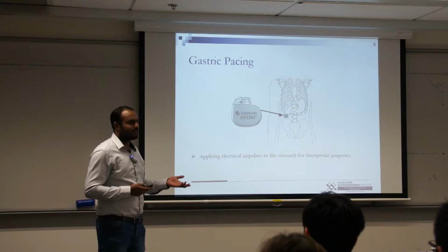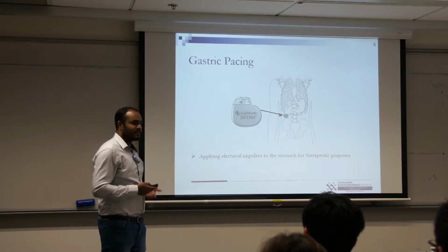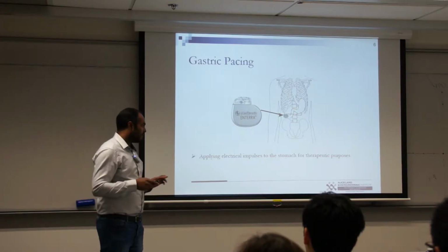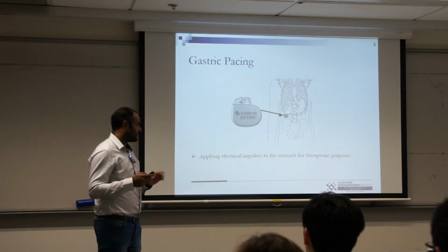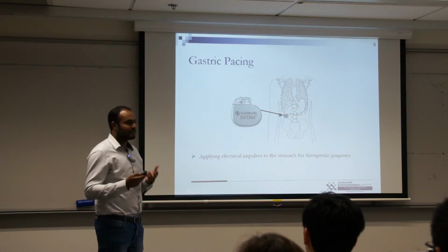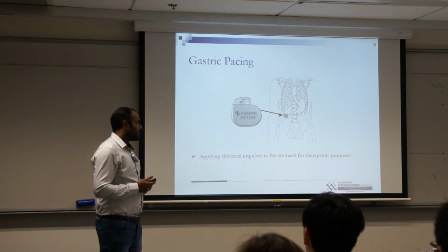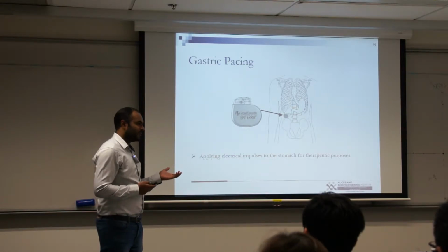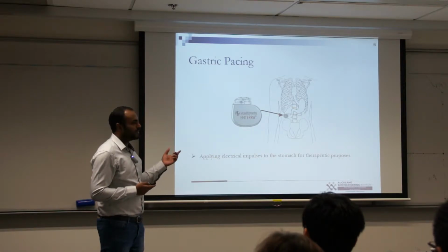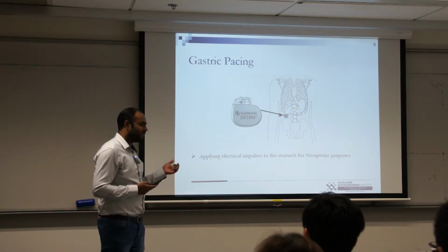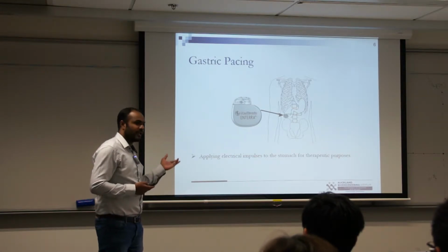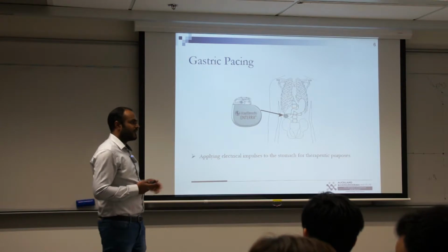There are several ways by which gastric electrical stimulation has been applied in the gastric field. It has been shown to have a therapeutic, curing effect. Most importantly, gastric pacing, whereby you apply high energy, low frequency signals. The pulses would be around 300 millisecond width and of high energy, and that will be applied onto the stomach, which can modulate the underlying slow wave activity.